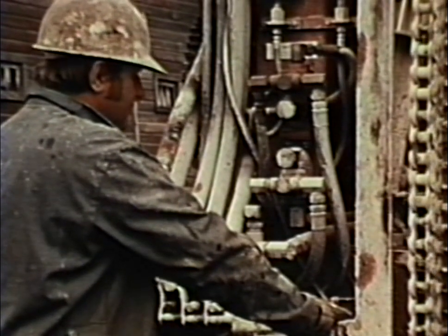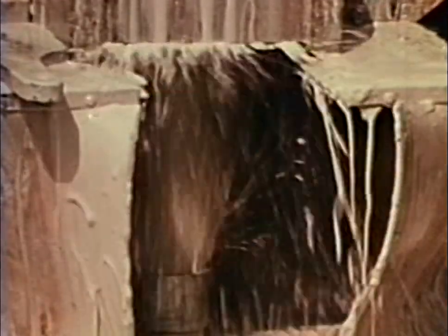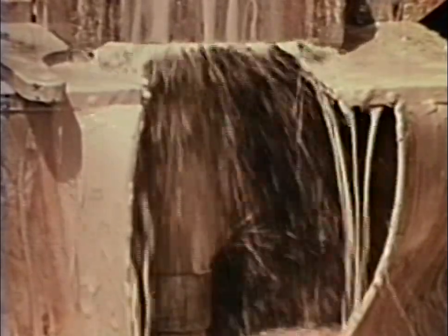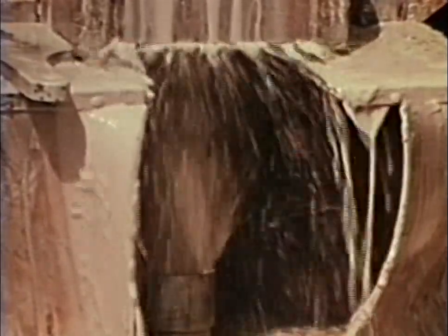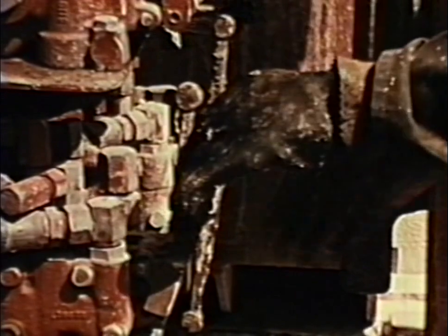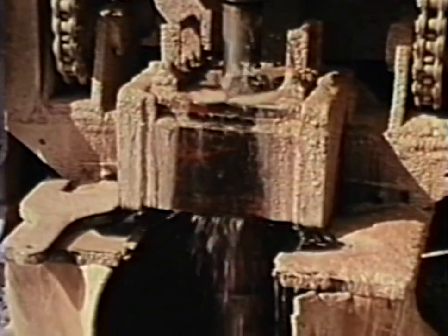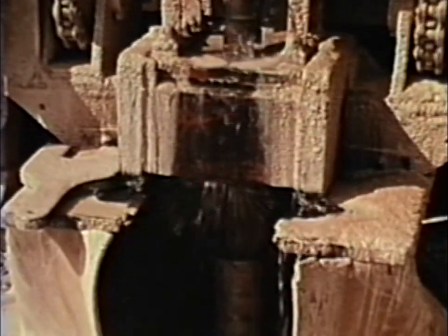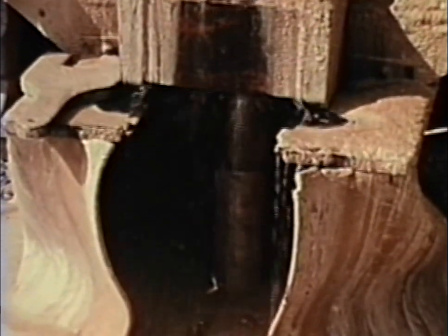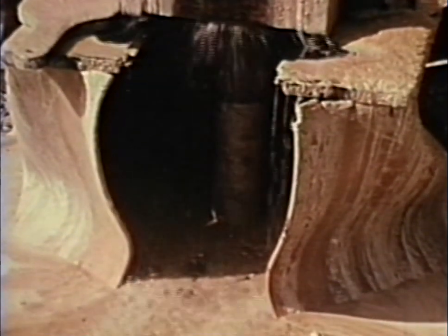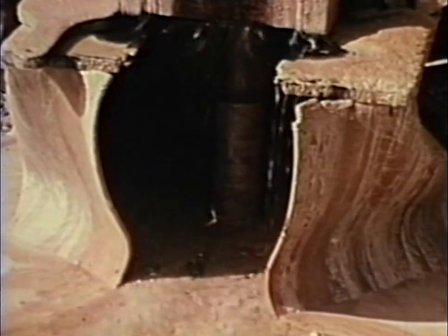When an aquifer is encountered, the drill mud can be removed by circulation of air or water. As the mud is flushed from the system, water from the aquifer gradually becomes the discharge from the hole. A steady yield of clear water is confirming evidence that a groundwater reservoir has been located.